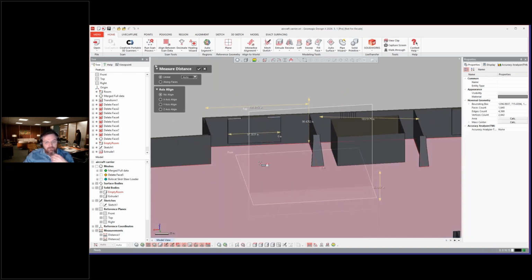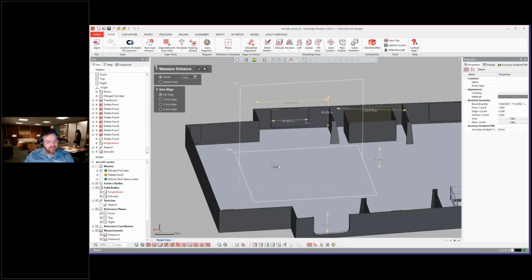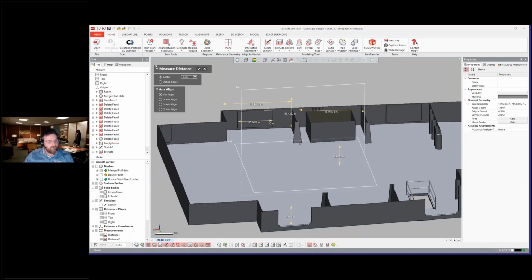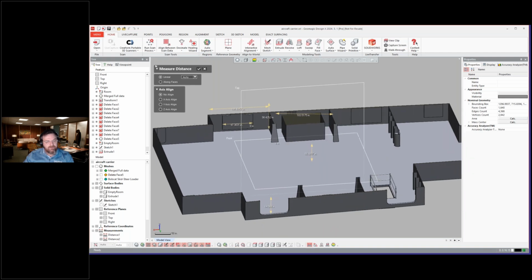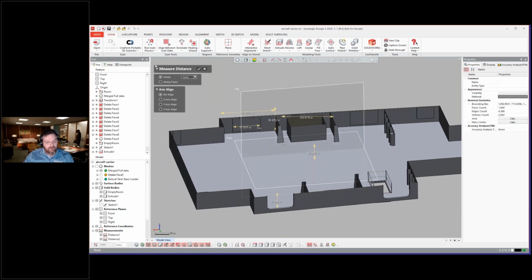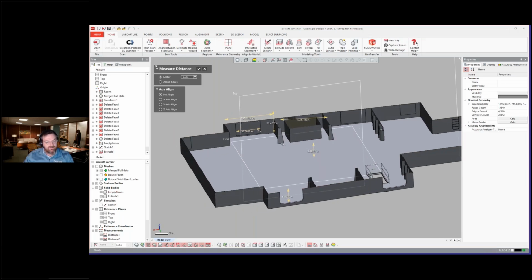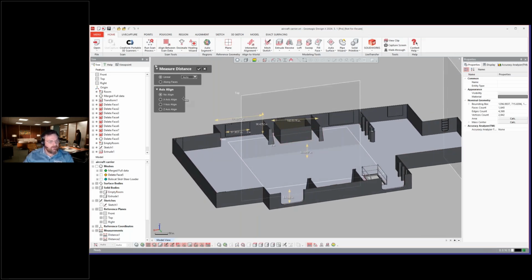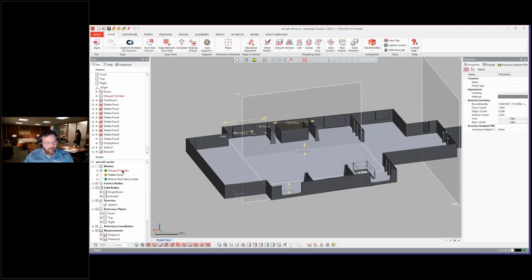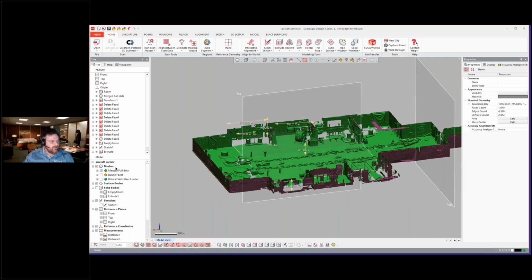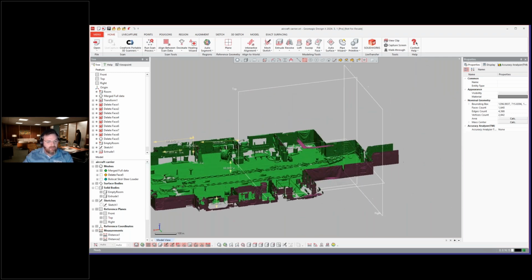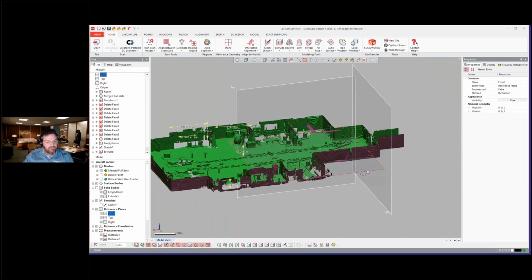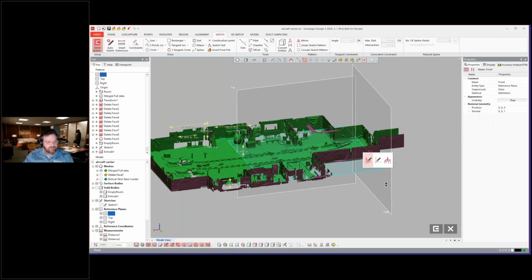And you can even use sketching to help you get some of those dimensions as well, all right? So as we talked about in the last example, if I cut a cross section through a profile, I can draw out sketch entities and then use the dimensioning tools within there to create dimensions as well. So if you want to see that real quick, I can turn on my mesh and we can come over and just click on this and say I want to create a mesh sketch.